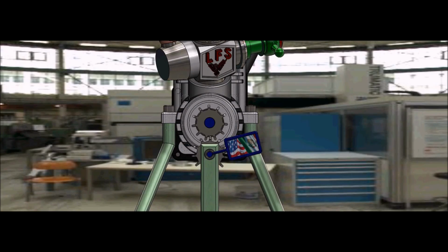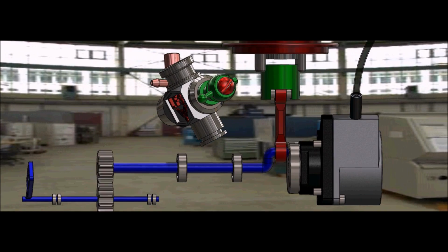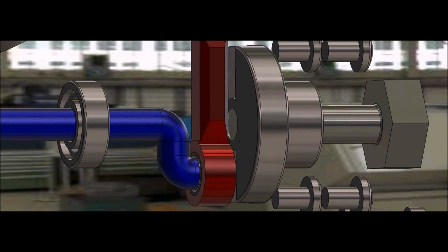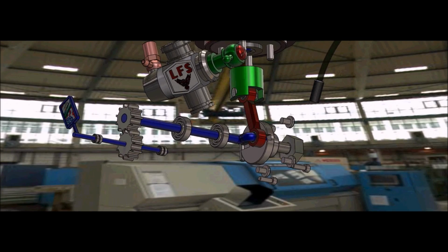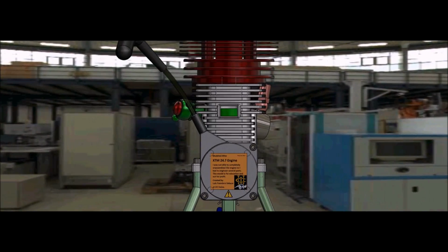Several different mates were required to make the engine function as expected. For the gears, I used advanced mates. Mating planes parallel to each other was used for all other rotating components. The piston moves up and down because it is connected to the shaft and is concentric to the engine block.